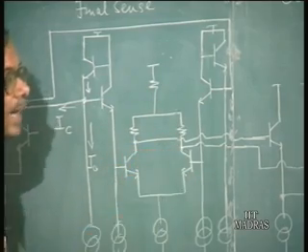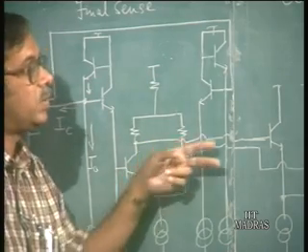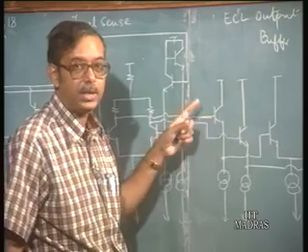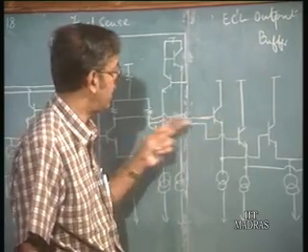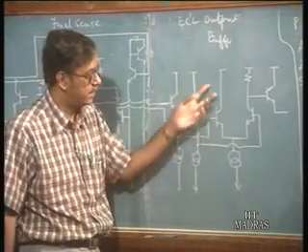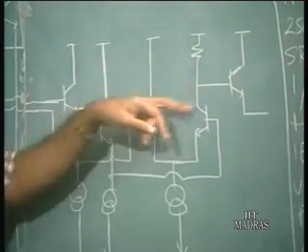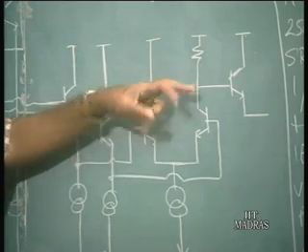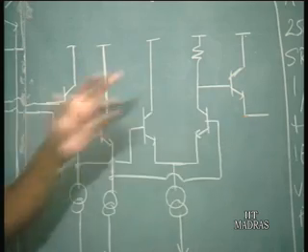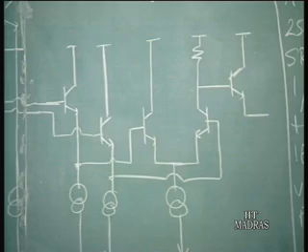So, again you are going to have a difference voltage between the two collectors, which is then followed up. This is the output buffer, basically the next stage. So, you have the emitter followers again from the previous stage, and then it is fed again to a differential amplifier stage, or an ECL stage, whatever you call it. Now you require just one output, a single-ended output. So, this output is going to be fed here, and whatever information you have is then available at the output. So, that is how the reading is done.